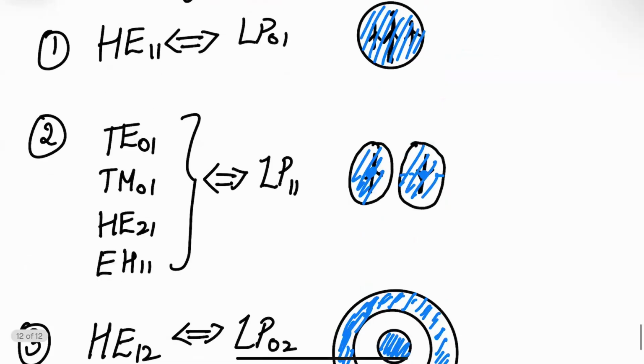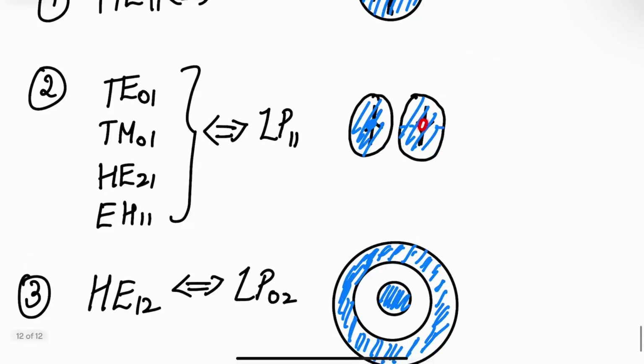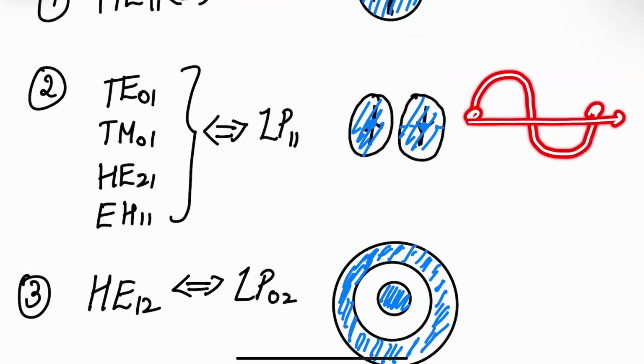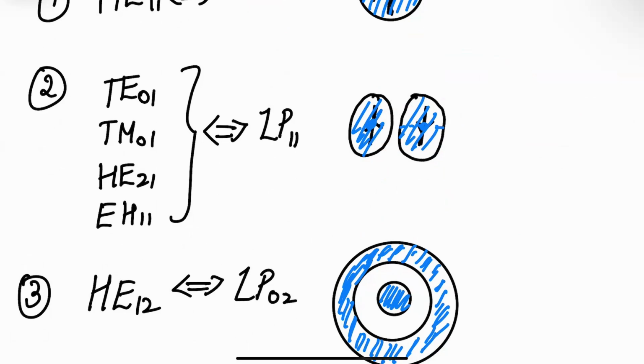Whereas if you pick the first index as 0, as you're going around in phi, there is no maxima or null. Here, as you're going around in phi, there are basically two. The reason there are two is because it's a cosine function. So I'm just saying that there's one cosine along phi. One cosine has two maxima, I guess, right? One there and one there, or two nulls. And that's why you have one cosine going this way. So here there is zero cosines, right?